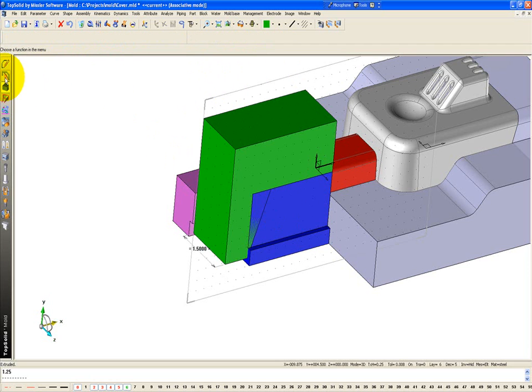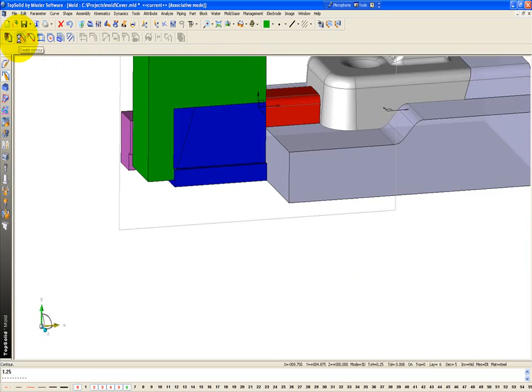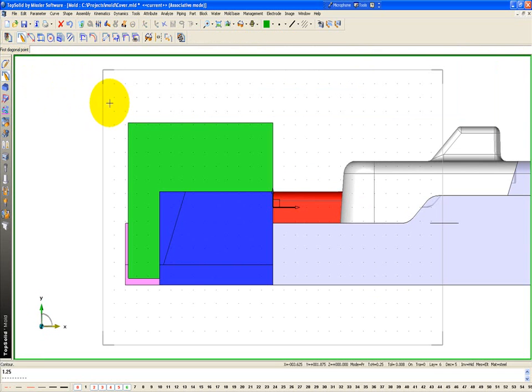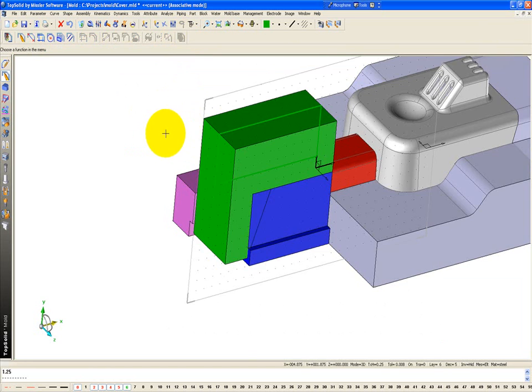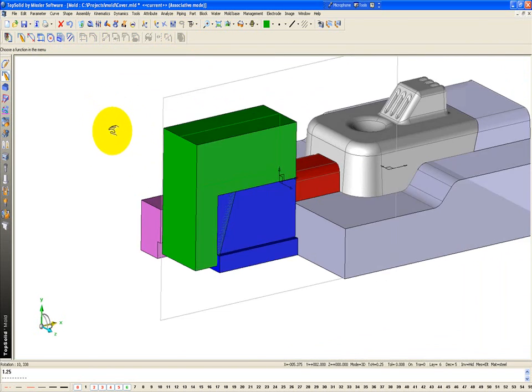Now I'm going to start another new sketch because this is too thin. I want to add some heels on both sides. So I'm going to start a new sketch. This will be rectangular. Add some relationships of coincidence again. That to that, that to that, here to there, and here to here. Okay? I'm going to exit out of that, and I'm going to use that sketch to create a boss.